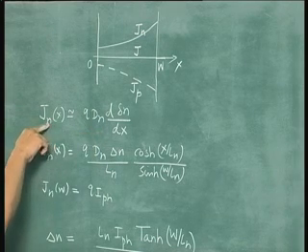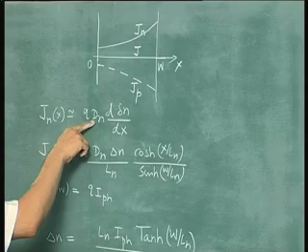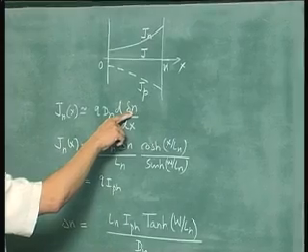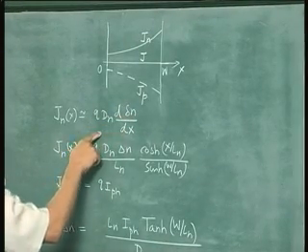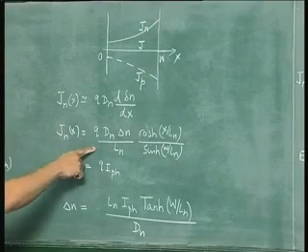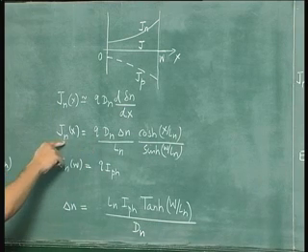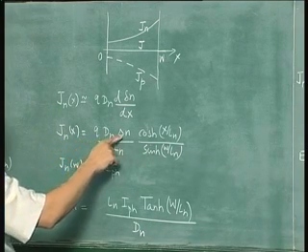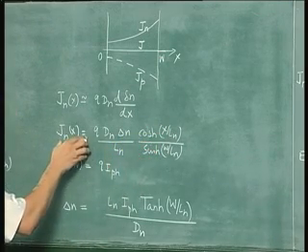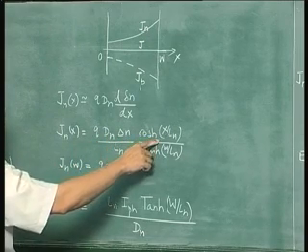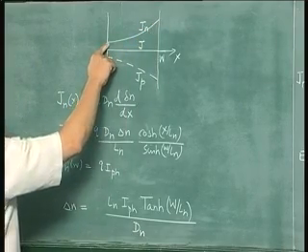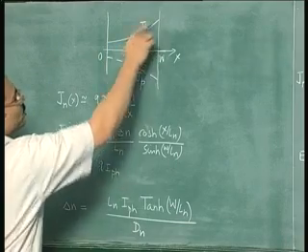Let us see how the current distribution will give us the value of delta N. Now Jnx, that is the electron current by diffusion approximation, is given by q Dn times the gradient of the excess electron concentration. So substituting for delta n from here, we can get this equation: Jnx equal to q Dn delta N upon ln into cosine hyperbolic x by ln by sine hyperbolic W by ln. So Jnx is of the form of cosine hyperbolic x by ln. This is clear from here. You see the shape, it is non-zero at this point and then it goes on increasing. So this is the shape of the cosine hyperbolic function.